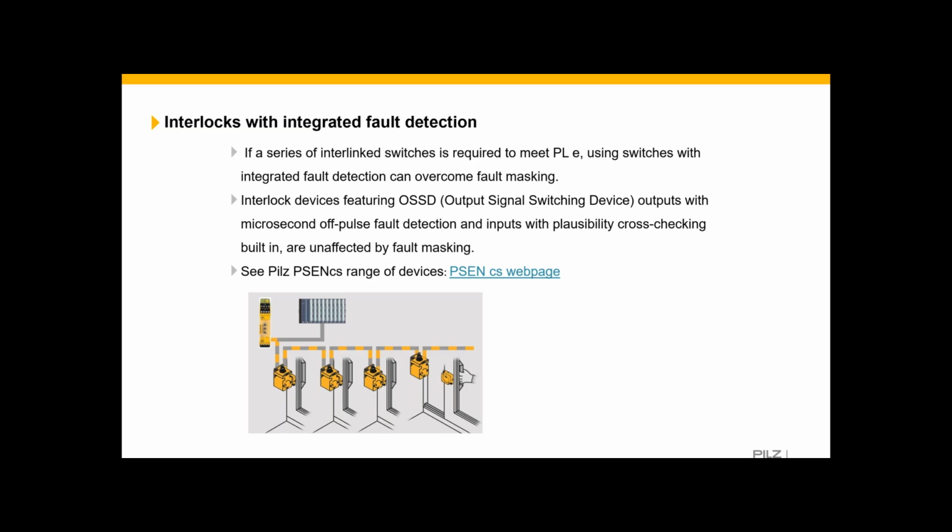Effectively what's happening is the switch to the left is basically checking the output of the switch to the right. And it's an RFID frequency, so there are no internal moving parts. So it could be IP67, IP66. That could be achieved. Then you could have temperatures from -25 up to +70.